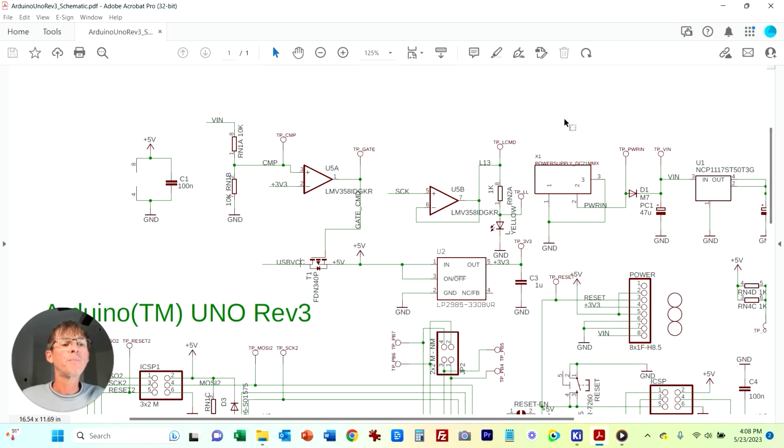Now let's assume that you don't have this plugged in. So you've got 0 volts here, while the negative is definitely higher. 3.3 is higher than 0, so that means this goes low. This going low turns on this FET, and it allows the USB 5 VCC signal to then feed the 5 volts.